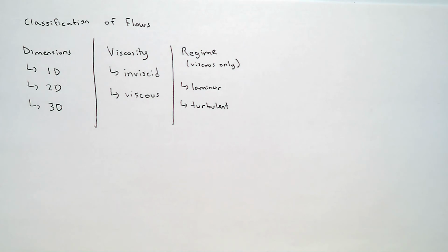So turbulent flow, the reason it's hard to predict is that it is chaotic. A very, very small change in initial conditions gives me a completely different change in final conditions. And the reason it is so chaotic for us from a mathematical perspective is that in order for us to model turbulent flow accurately, we need to consider every possible element that could influence that flow. So we're not just talking about pressures, stresses, and temperatures.